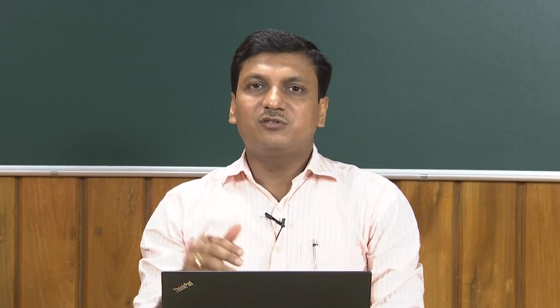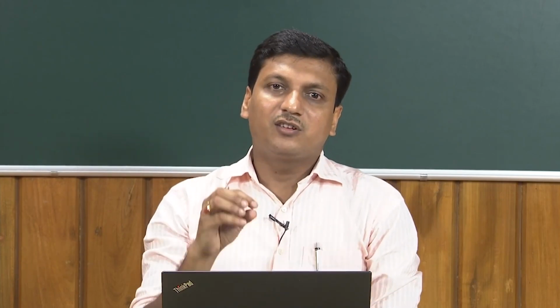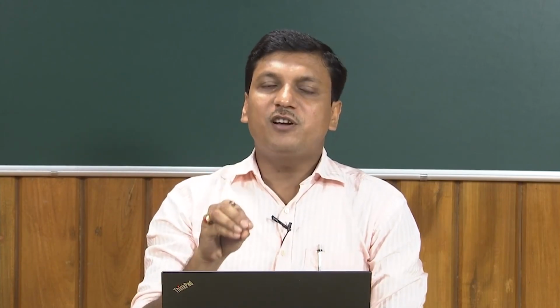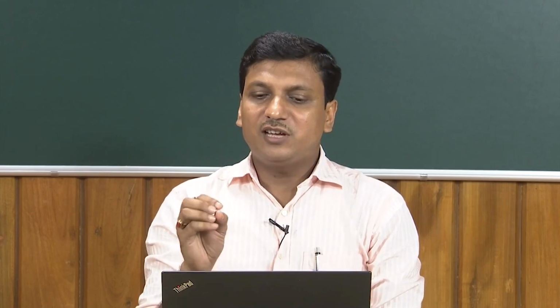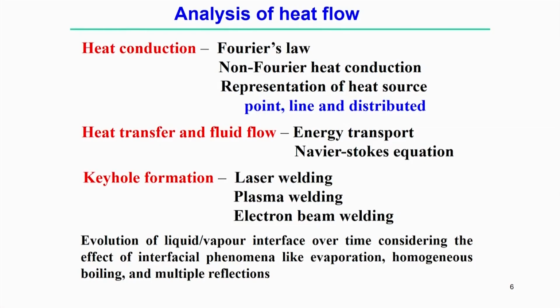In this case we normally solve the conservation of mass, momentum and energy equations. The energy equation is what we consider in the heat conduction equation, but in this case the extra term is the energy transport due to the flow field of the material. So that term is added, and it is necessary to solve it along with the heat conduction equation.